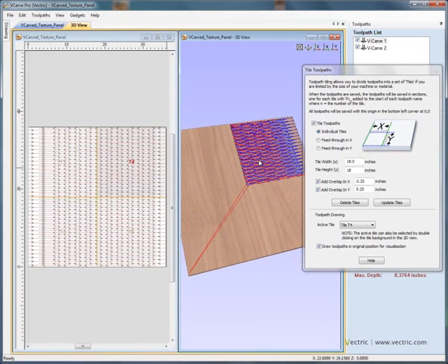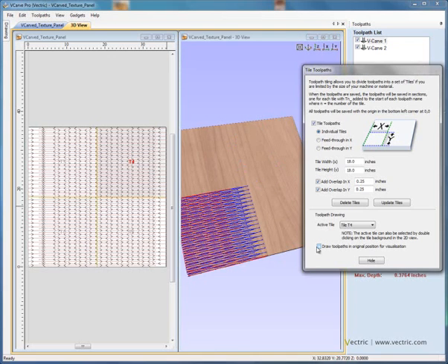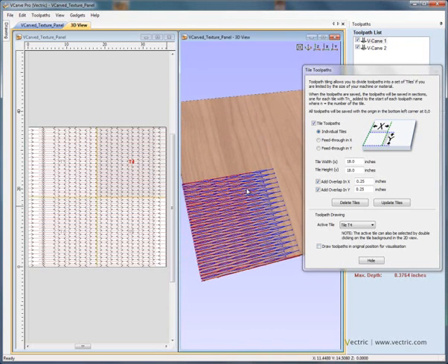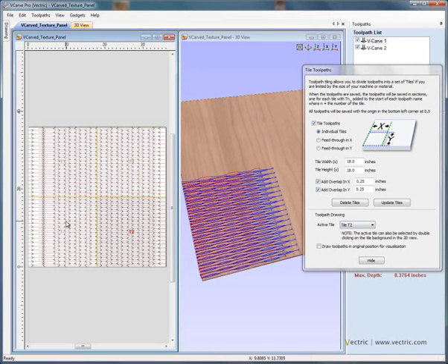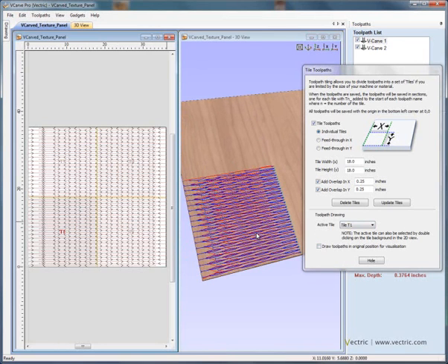Now, saving the toolpaths for tile number 4 up in the top right hand corner isn't going to be any good in helping us cut this on a smaller machine table. What we need to do is move this toolpath data into the bottom left hand corner. To do that, we simply say draw the toolpaths where the tile is going to be positioned, not in the original position. So switch this off and the toolpath segment gets moved to the bottom left hand corner. And this is the same for all of the toolpath segments. They're all being shifted to be in the bottom left hand corner to make them machinable on a smaller bed size or into a smaller piece of material.